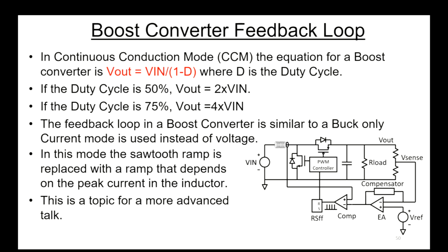I don't want to get into this in any great detail, but what I'm really trying to tell you is you're almost locked into using this current mode feedback if you're going to be doing a boost converter. Voltage mode or voltage feed forward mode isn't going to work. You're going to have to do this current mode. But this is a topic for a more advanced talk. We'll get Moni or James down here, one of the buck guys, to talk about this.